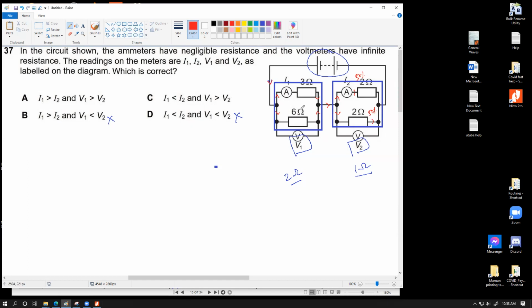But if you have a look over here, this resistance is big and this resistance is small. So between these 2 branch currents, which is supposed to be bigger? Which branch should have higher current between these? Sir, the branch with 3 ohms. The branch with 3 ohm, because that's a smaller resistance. So even if you don't bother to calculate this, I can simply write that the current through this pathway should be bigger than 50%, and the current flowing through this branch should be less than 50%. Now if you compare I1 and I2, I2 is exactly 50% and I1 is bigger than 50%. So between I1 and I2, which one should be larger? I1. So ultimately we are getting this as our correct response.